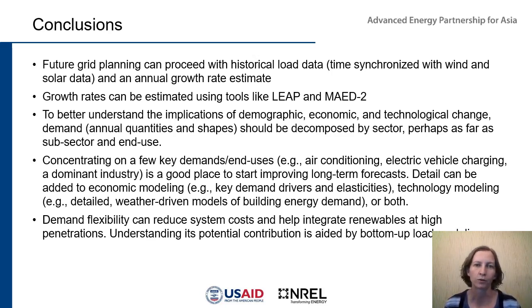If you do take that approach, and if you are looking out 5, 10, 20 years into the future, then you'll also want to come up with an estimate of annual growth in electricity use. You can do that by projecting historic trends, or you could also use a tool like LEAP or Made2 to help you come up with those estimates. If you want to go further, then you'll probably want to tease out different components of load. You might want to break your load down by sector. In some cases, you might want to look at subsectors or end uses.